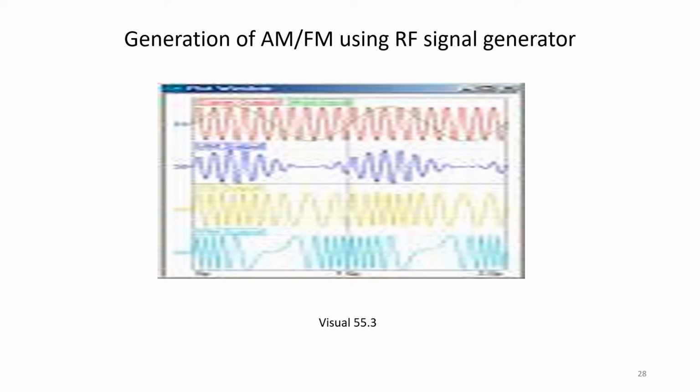So here, as I told you, the applications of the signal generator: it can generate various RF voltages required for alignment and servicing of radio equipment, testing of amplifier response, adjusting of amplifier response, alignment of radio and television receivers, troubleshooting and repairing electronic devices, checking and testing various lab experiments, generation of AM, FM modulated waves for testing communication receivers.